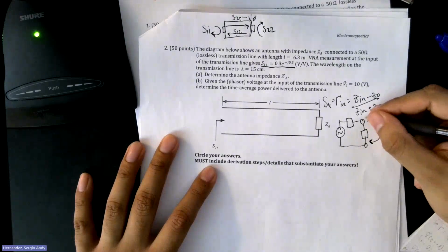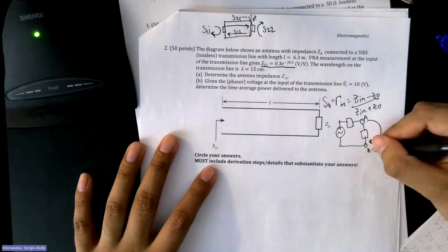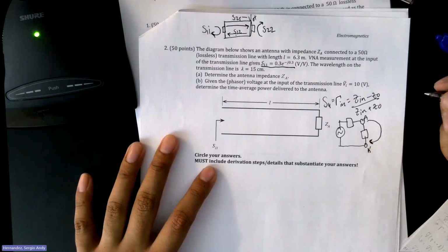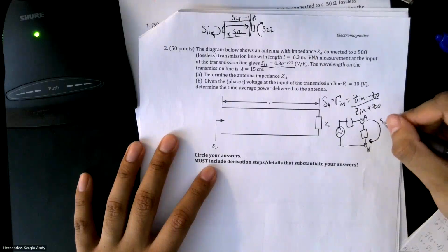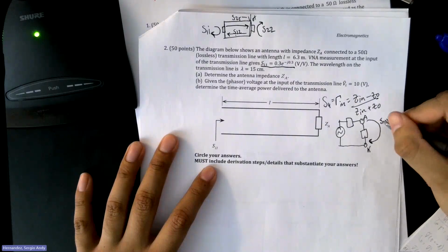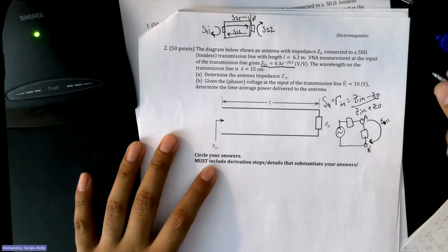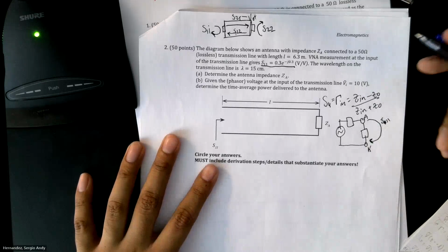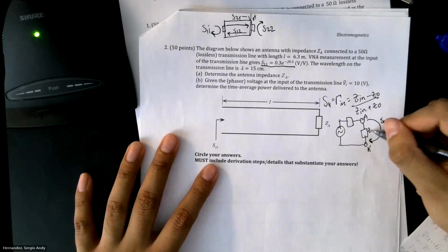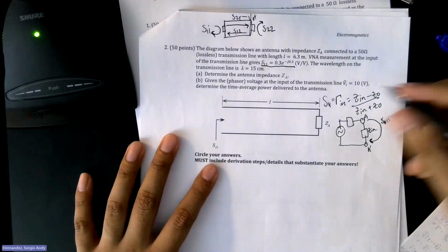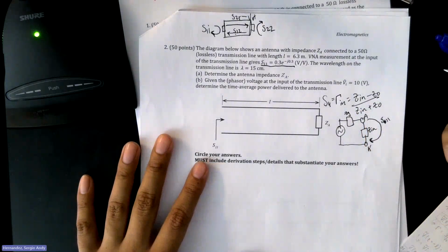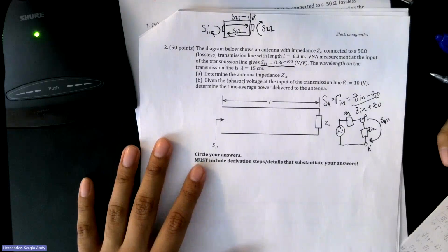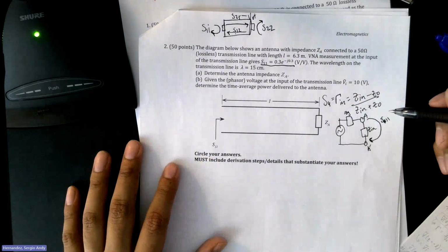You input a signal here at point A, and you want to measure how much is coming back at point A in real time, right? So this is your S11 measurement. A to A prime, right? And you're measuring what exactly, the voltage from A to A prime in this case? Yeah, so just the one that gets returned.